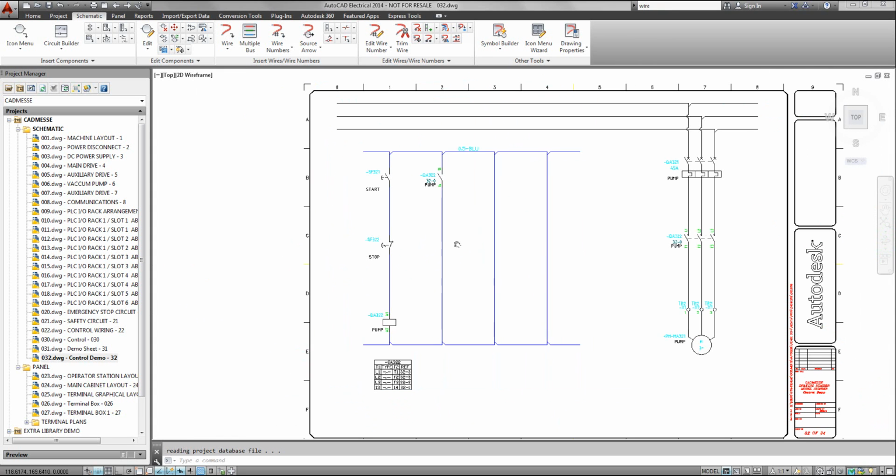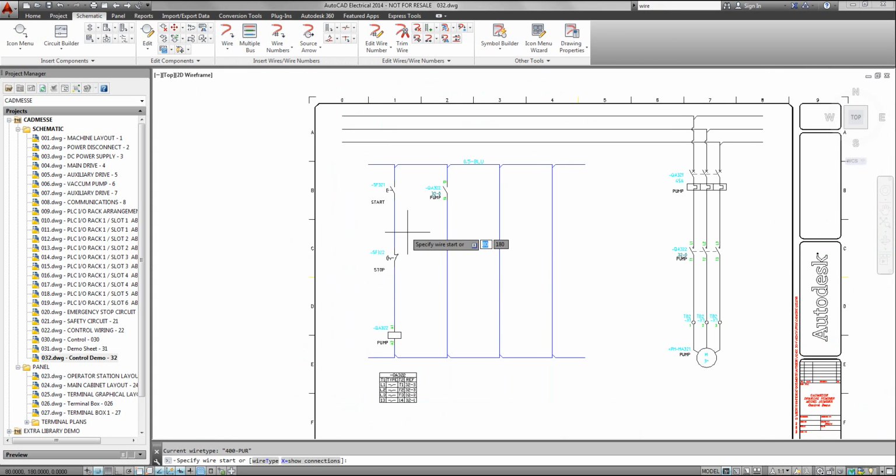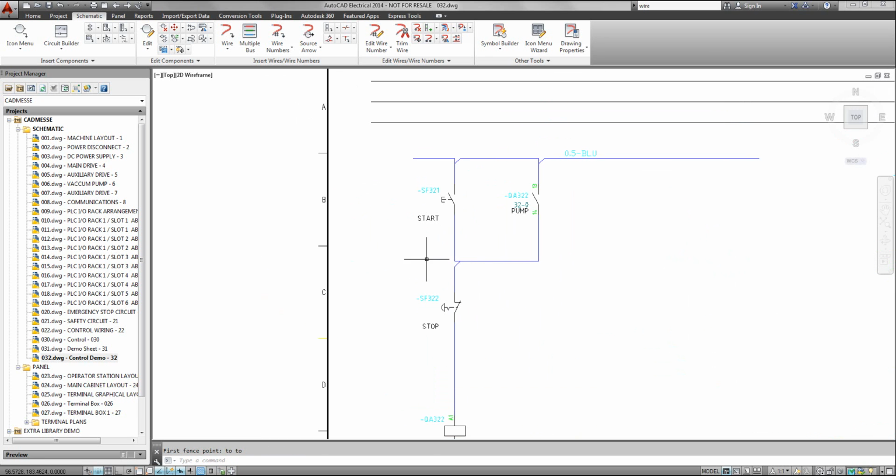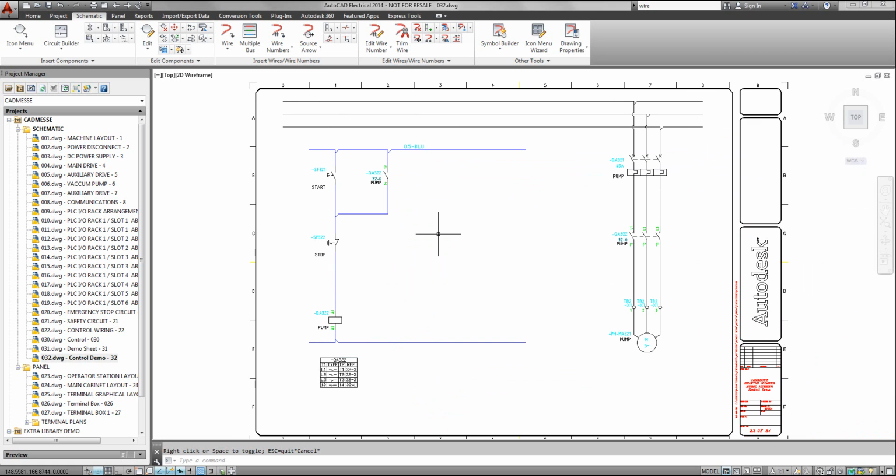So I'm just going to tidy up this circuit now. I'm going to use my wire tool. I'm going to create a link there, so like parallel, and then I'm just going to trim the rest of the wires that I don't intend to use using the fence command again, like so, and gets rid of all the wires. You'll notice here actually my angle for my T is not really facing the right way. I can actually adjust that if I right click over it, use the toggle angle T markers, and then just tap the space bar into this new orientation I want it to be, so it looks the same as all the others. I escape the tool after that. So that's basically our circuit.